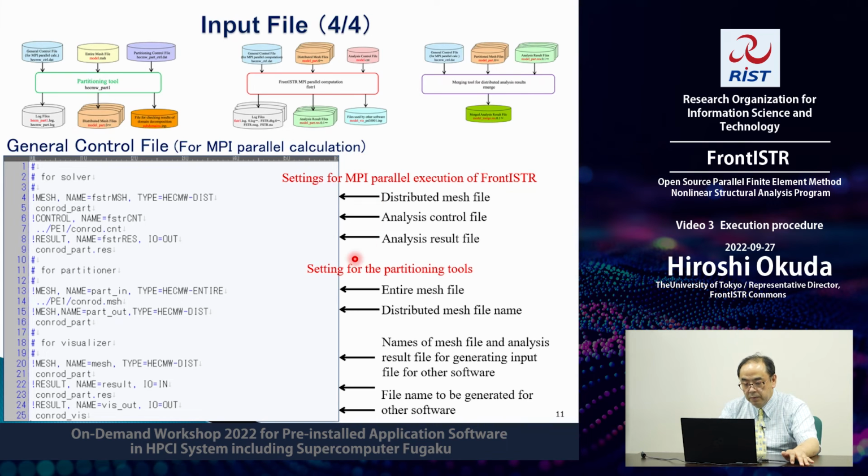If you are going to carry out parallel finite element computation, you need to specify some information about the partitioning tools. So we have to consider a small difference in the general control file between the sequential and the parallel computations.